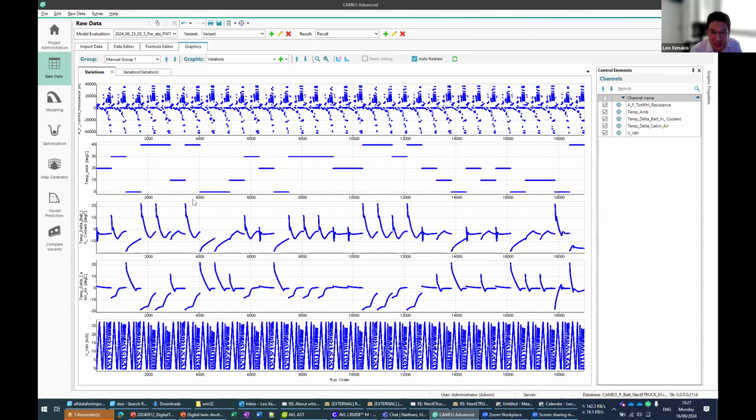Yes. Okay, but we have the time axis along the bottom. We basically concatenated all the cycles that we've run, and we can see here essentially the inputs that we used to the models. So what we really varied was the vehicle speeds that we saw, and we fixed the ambient temperature for each of these. And you can see here, for example, that we have a delta between the coolant temperature for the battery and the actual battery temperature.